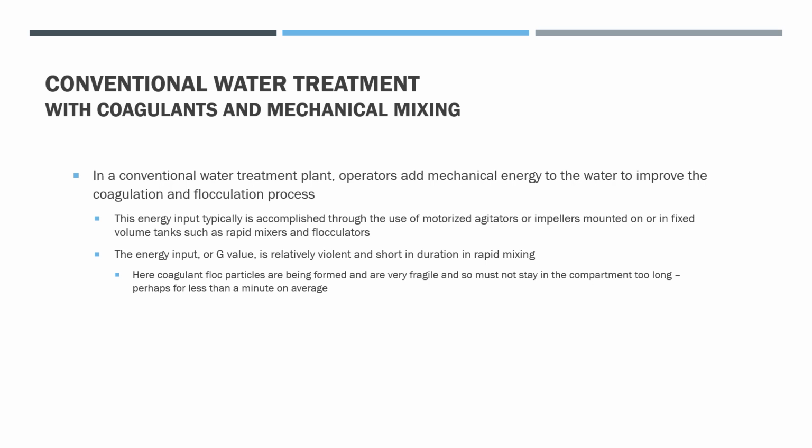Here we're making small floc particles being formed. They're initially very fragile, so we can't stay in that rapid mixer compartment very long. We've got to be in and out very quickly, usually less than a minute on average. In Ohio, again, 30 seconds or less.